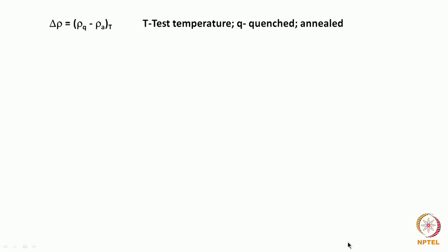Then that same sample, if I heat it at a very high temperature and then quench it, when I quench it, what is going to happen is that all the vacancies should be retained. Here we make an assumption that in reality what happens when you quench it fast, some of the vacancies condense to form dislocation loops, vacancy loops and all these things, and they get annihilated. We make the assumption that the same concentration of vacancy is retained. That is the first assumption which we make.